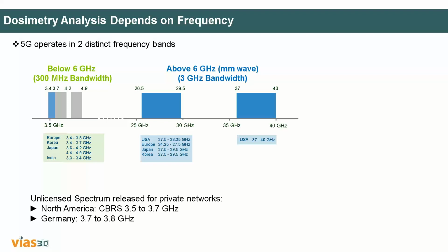If you have building construction, a concrete wall or a glass, it has a different frequency response, right? It is the path loss. At 3.5 gigahertz, maybe it will give you only 17 dB, but at 26 gigahertz, it will give you 24 dB path loss. So again, that is most important.